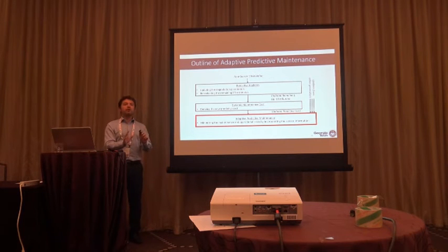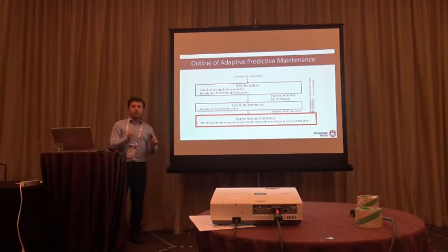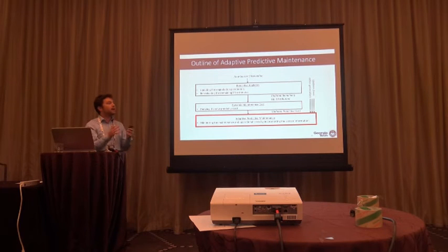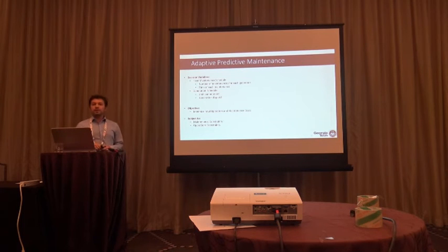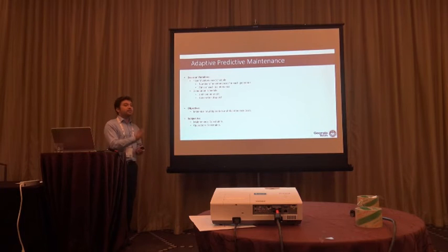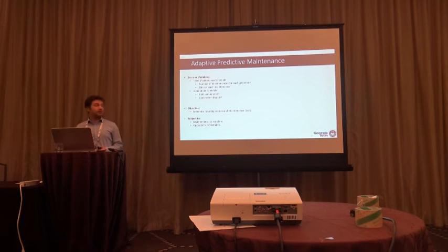So far what we have done, we have been focusing on a single power plant or a single generator. We can now think that this process is happening for every power plant in the field in parallel. So in real time, we are using this number of modules, predictive analytics and dynamic maintenance, for every generator in the field. What we want to do is feed those dynamic maintenance cost functions that are updating in real time into an adaptive predictive maintenance framework. And we actually provide a comprehensive optimization problem for operations and maintenance scheduling, whereby we look at the maintenance schedule, we decide on how many maintenances to schedule for each generator and also the time of each maintenance,